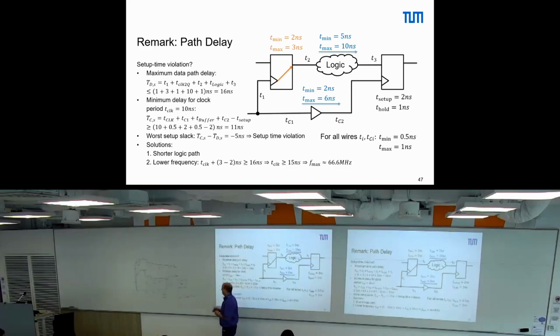If we do a timing analysis, the tool searches the critical path and does this check. For each path, it computes this difference and gives you some slack. It does not do the comparison directly. If it's positive, then you're lucky, you met the criteria.